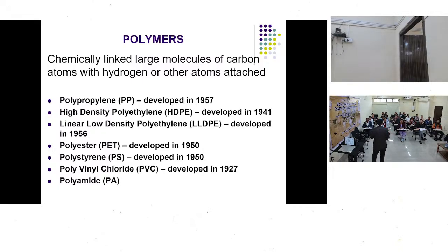And it's not even necessary to remember when these things came into being. The only idea is that you should know that these are polymeric materials used to make geosynthetics. Why? Because once you are going to interact with people, suppose for example, you want to have a geobag, okay? And now you ask for a geobag through a certain contracting agency or a manufacturer. And he says, sir, I am giving you a geobag of HDPE. And you get confused. You say, no, what is HDPE? So what will happen is that you will immediately say, okay, whatever it be, you just give it to me. But no, you should know it is a high density polyethylene.